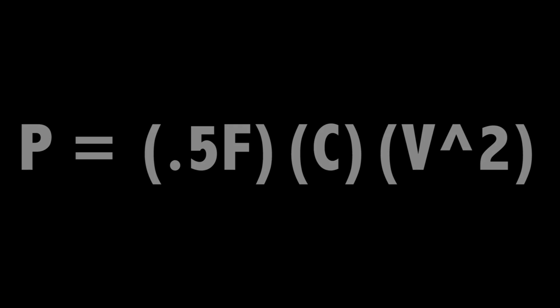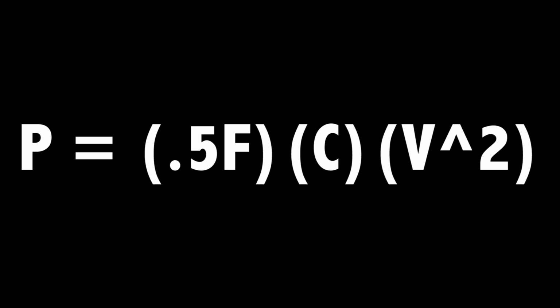So we can see that quite a bit of power is going to be needed if we want to keep up with our performance drives. Now, looking back at our equation, there are some key ways that we can reduce this power consumption. Since power is proportional to V squared, if we reduce V, we substantially decrease the amount of power consumed by a CPU.